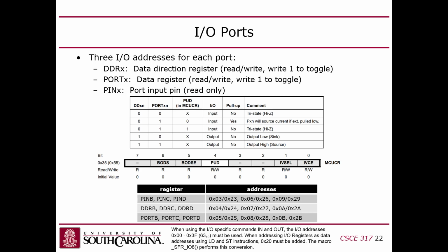You guys with me? So you can set up the pins to be inputs or outputs, and when I say pins, I mean the 23 pins that span ports B, C, and D. You can set each pin up as an input or output. If it's an input, it could be pull up or not. And if it's an output, you just set port to use the output. If it's an input, use port to set the input mode, and then pin to read the input.